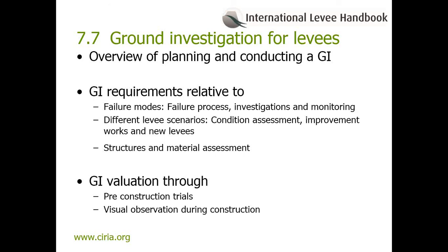GI should not finish on completion of the intrusive investigation. In special circumstances, it may be extended to pre-construction trials and should include visual observations on site during construction, where long sections of new levee are to be constructed or existing levees substantially raised over soft ground. The cost and construction risk can be high. The use of instrumented pre-construction trials can be used to reduce these risks through loading the ground to failure and using back analysis techniques to evaluate soil strengths, or, if not loaded to failure, determining in-situ field consolidation parameters.